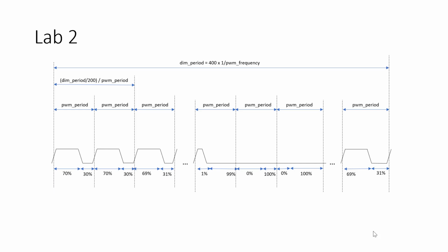Does that make sense? Okay, so just keep that in mind, because you can structure your loop in your code to just keep track of this number, this ratio. This is the important ratio. And then every time you have iterated over the PWM period that many times, you adjust your duty cycle. Okay? Does that make sense? Hopefully, if you're still working on that, that's a hint.